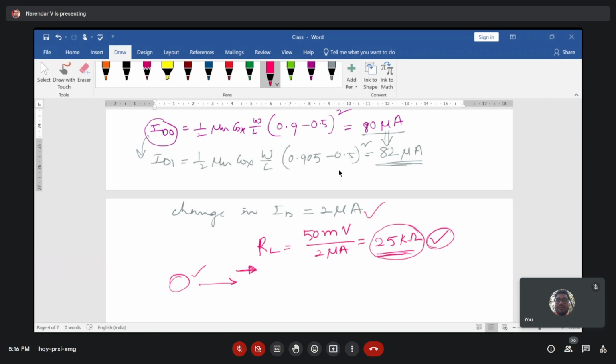So this is called the requirement of biasing. In some interviews, people may ask you the question, what is the requirement of biasing? Biasing is required to amplify a given signal, to make a device on. It gives the ability to the transistor to amplify, or it gives strength to the transistor to amplify effectively, so you require a biasing.